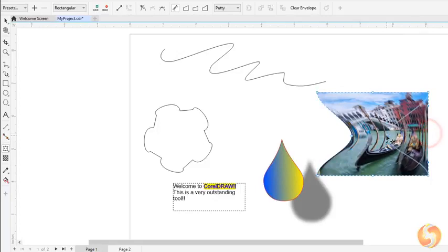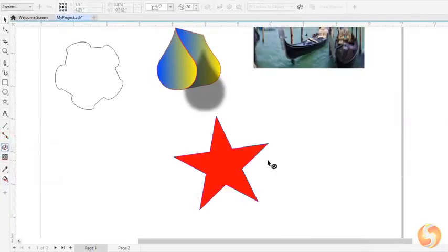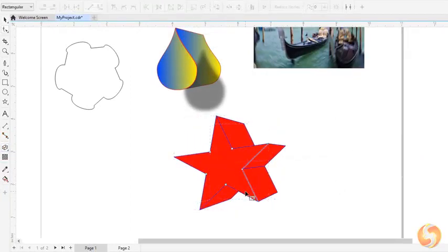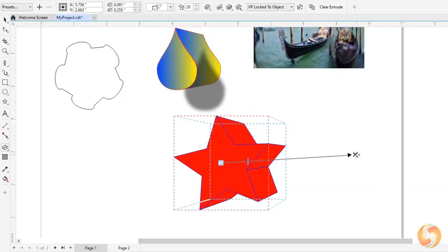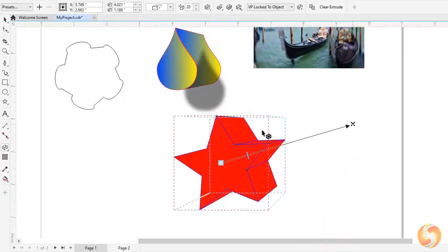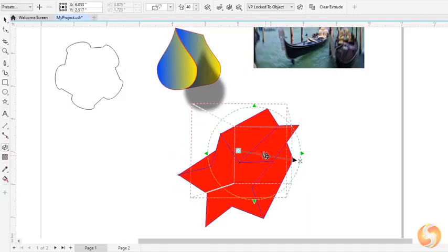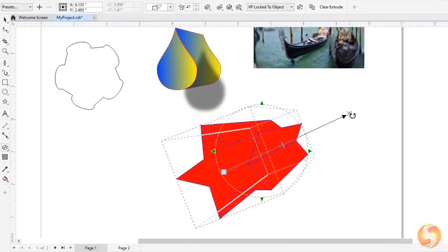Select one and click and drag to apply it. If you enable the Extrude tool, you will add some 3D extrusion that gets updated in case you edit its basic shape section. You can adjust its direction with the black cross and its total length with the small white block. Always with the Extrude tool, you can click once on the extrusion and click and drag to rotate it, or drag from its green circle to rotate around its axis.